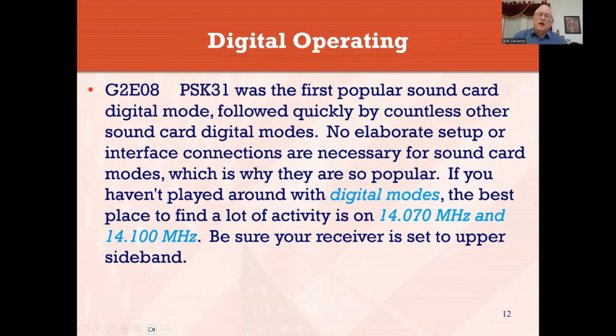PSK31 was the granddaddy, right? It was right after teletype, the first popular sound card digital mode. And of course, a lot of things came on since. FT8 is the big bird right now. It didn't require an elaborate setup or a whole lot of equipment to use the computer's sound card. Generally you just had a little interface box that would take the sound out of the radio and run it through the box into the computer sound card's input, and the output from the computer would go through the same box, get processed a little bit, and be sent into the radio mic connection. And then there would be a signal so that when you wanted to key the transmitter, it would send a keying signal to the transmitter, and it would transmit when it was told to do so.